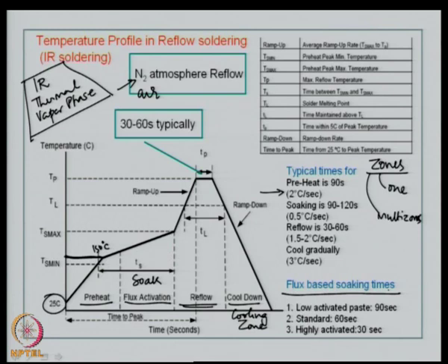The solder paste contains flux, as you all know. It also includes some kind of an adhesive, because it helps in pick and place. It contains an epoxy media, and it contains flux. Flux is necessary for soldering, we have seen. It improves wetting, it prevents corrosion, and so on. We have also seen different kinds of fluxes in our previous lectures.